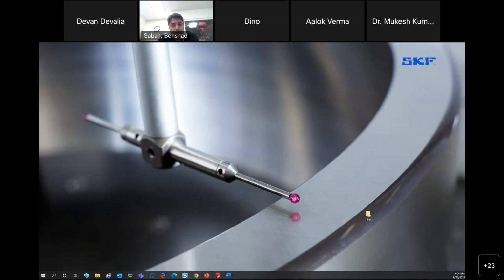As temperatures are elevated, we know from chemistry that heat speeds up the reactions. So higher operating temperatures accelerate this aggressive chemical reaction. And if we're not careful, that's why at SKF we do not recommend EP to be used above 80 degrees C.